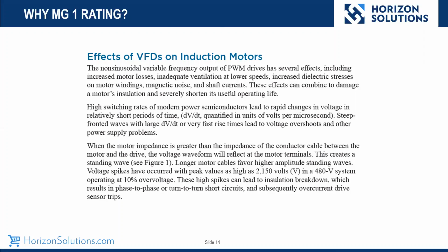So basically, MG1 was brought on to address some of those issues. Motors were burning up all over the place. Motor manufacturers were pointing fingers at drive manufacturers, and the problem really wasn't resolved until MG1 took effect. About the early 90s to mid 90s, we started to see the IGBTs definitely come into the marketplace, and basically they were predominant over their predecessors.